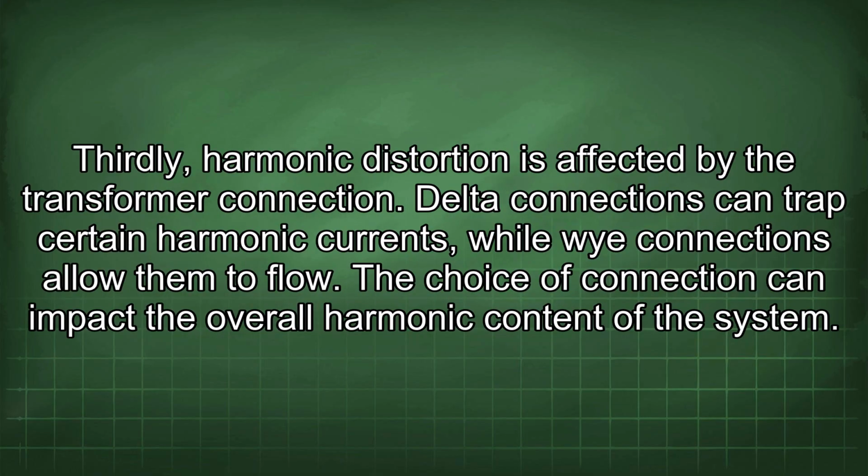Thirdly, harmonic distortion is affected by the transformer connection. Delta connections can trap certain harmonic currents while Y connections allow them to flow. The choice of connection can impact the overall harmonic content of the system.